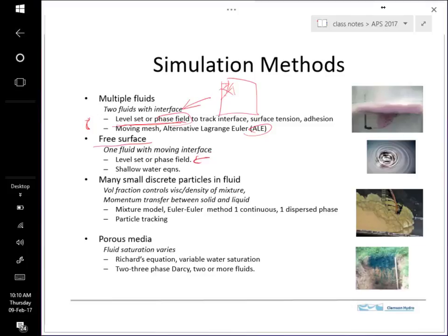And one approach that has been developed is to recognize that a lot of flows are much bigger laterally than depth-wise, a lot of free surface problems, like in the ocean or the atmosphere. A lot of water bodies are shallow relative to their lateral dimensions. And so what you can do is take the Navier-Stokes equations and simplify them to account for that. And so you're then including that free surface without having to deal with what the air is doing. And actually you're simplifying the overall problem.